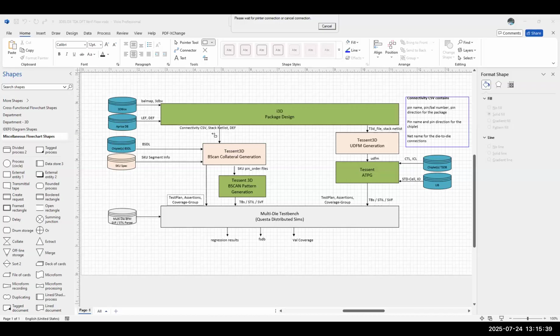So the idea is that this TDK would hold the information in the chiplet relating to the test IO primarily, and there's other stuff that we put in there, other information and properties. But the idea of the TDK is to provide whatever collateral is necessary to enable a SIP DFT engineer to test this chiplet along with other chiplets that he may be designing himself, or they could all be coming from third parties. So having said that, Bala, does it make sense to have this information for a chiplet in the TDK?